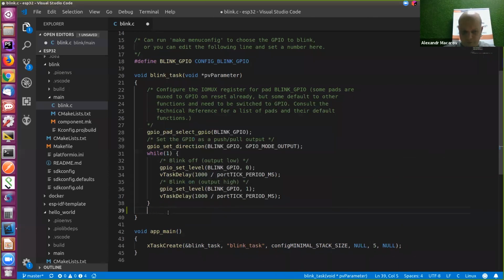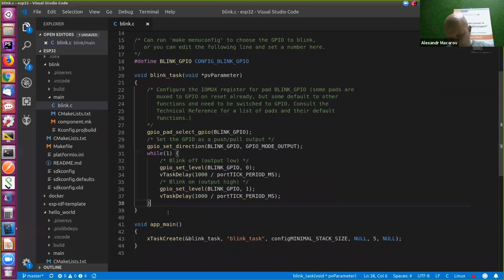If you want to delete it for some reason, you need to do a vTaskDelete inside here. And as a reference, you need to pass null because you are already inside the task. And here, if you have the reference, you can use the same function, but as the parameter, you need to pass the reference if you want to cancel the task outside of the code.